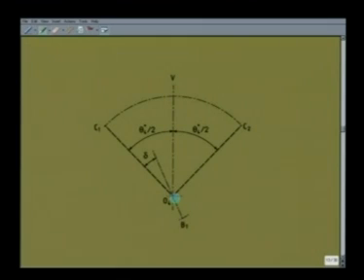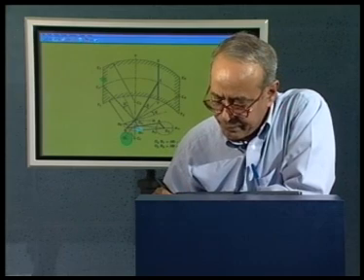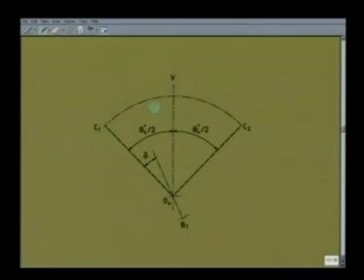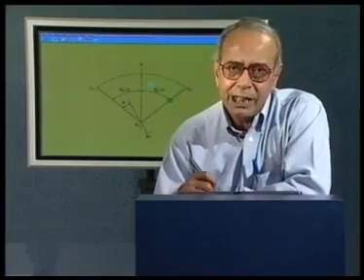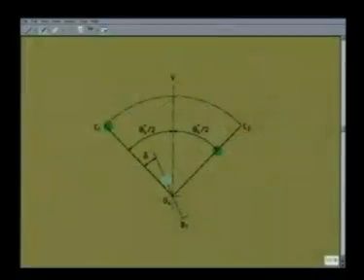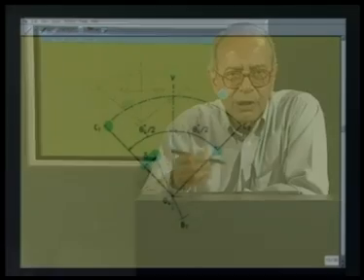We have already seen that B1, which is the extreme position of the link O4B, we have obtained earlier, that is this B1, and now O4C1 must be like this to make the field of wiping symmetrical, because now I have made O4C1 and O4C2 symmetrically placed about the vertical line at an angle theta 4 star by 2 and theta 4 star by 2, because theta 4 star is entirely decided by all the link lengths, which I cannot change. Now this is O4B1 and this is O4C1. So the extension of O4B1 and this line O4C1, the angle is delta. This is the angle delta which should be provided rather than what we had earlier as 16 degree.